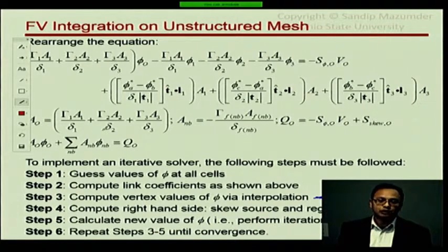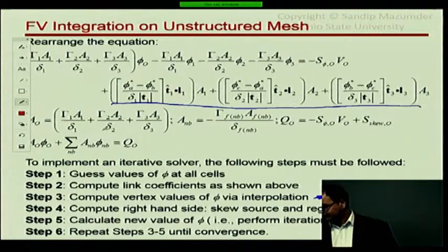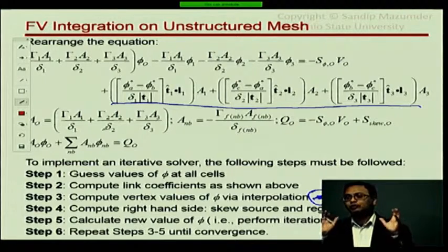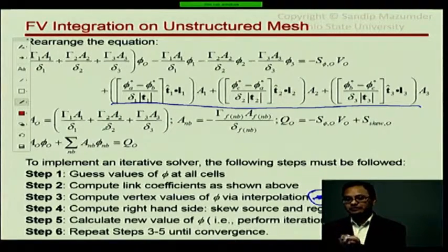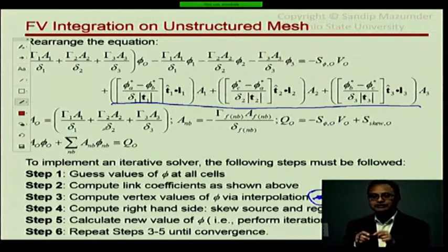We wouldn't have to do that in a structured mesh or a Cartesian mesh formulation at all. Why? Because we are getting ready to do this calculation. And again, you need to do it in a modular way. You don't want to do that locally and calculate vertex values again and again locally. You just want to call one function which will calculate vertex values for you. And the advantage of that is you can feed in any data structure.